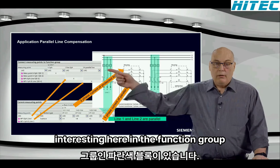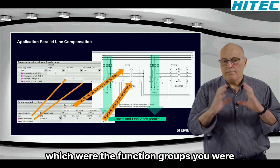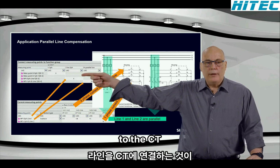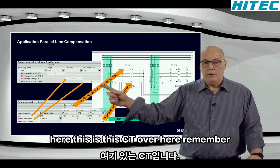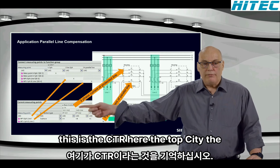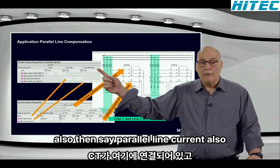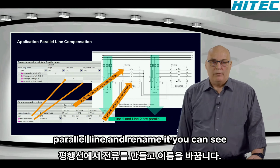And now interesting here, in the function group connection, remember we had the blue blocks, which were the function groups. You were connecting your function group line to the CT here. This is the CT over here, the top CT, the three-phase CT connected here. And you also then say parallel line current, also connected for the function group line, is that single-phase current from the parallel line.